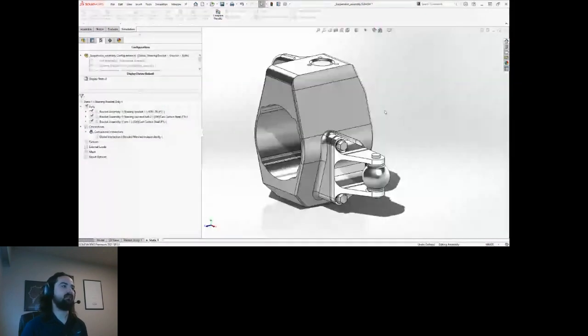So in this other configuration, we can now see that the steering bracket is fastened to the knuckle using these 3 screws. And the two components butt up against one another on these flat faces where they touch. And so I'm going to go ahead and represent the knuckle using fixtures because I haven't actually included the knuckle in the study. So back to the steering bracket configuration here.